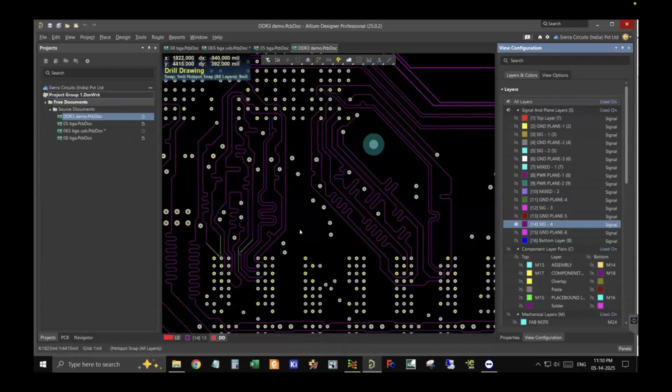So if you are going on an internal layer, for example layer 3, then all the 11 signals will be routed on layer 3 itself. That helps us keep all the signals in one layer so that it becomes easy for us to identify what is what. And secondly, it helps us when it comes to the via length. Whatever via length adds up to your signal whenever you go from one layer to another remains the same for all the signals in that particular data set. So the worry of something having added up to something is gone. That is why we try to route them on a single layer.